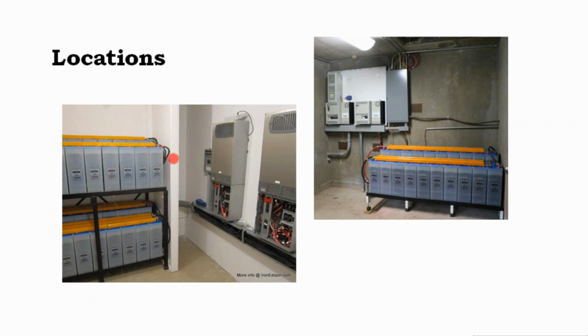And so, as I was saying yesterday, I've been able to go to my battery manufacturer and get permission to not open up the batteries every 2 weeks to measure the specific gravity of the cell as their warranty guidelines state, because I am doing the temperature regulation and current monitoring. So actually, these rooms still have electric code violations in them.